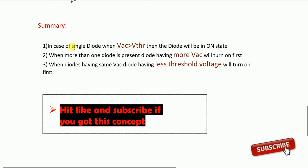So this is the summary, friends. In case of a single diode, when VAC is greater than V threshold, then the diode will be in on state. There is no confusion at all. When there is one diode, open circuit that diode and find out the VAC across that. If VAC is greater than V threshold, then the diode will be in on state. When more than one diode is present, the diode having more VAC will turn on first. So when 2 or 3 diodes are present, open circuit all the diodes and find out VAC across all the diodes. The diode which has more VAC will turn on first. After this, what you should do? Calculate VAC across other diodes.